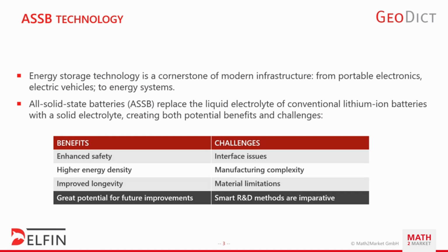But the challenges, of course, are also there. You have potential issues with the interfaces between the solid electrolyte and the active material. The manufacturing can be quite complex. Most of the materials used in the solid electrolytes are not hydrophobic, but very sensitive to humidity as well as oxygen. And the materials that are used at the moment may also be limited, so you may want to look into different materials that you can use for this technology. And all in all, smart methods and research and development are very important to make this endeavor a successful one.